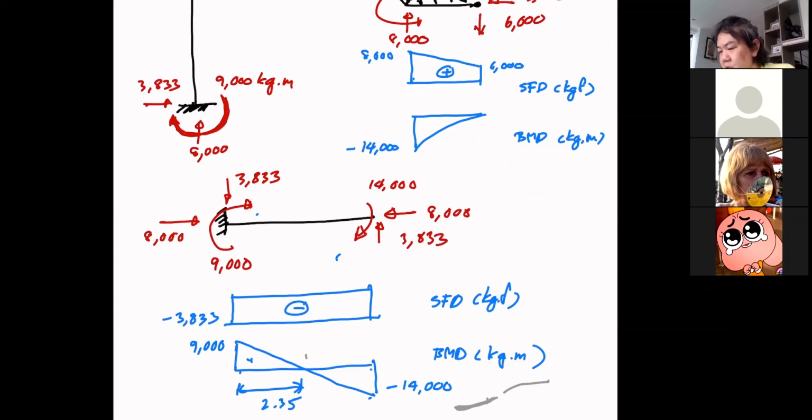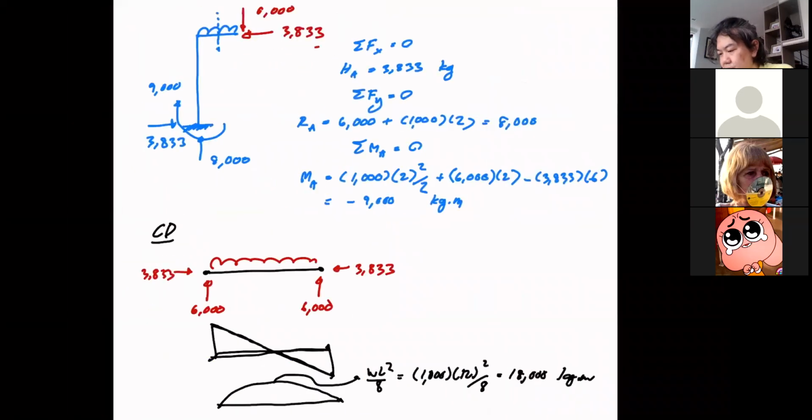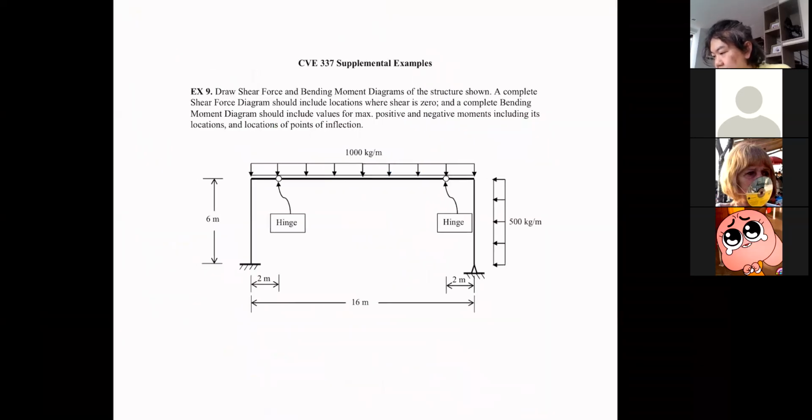So this piece will go just like this because of the presence of this, and because you have a 0 rotation there, so this frame is generally going like that. See? That's according to our bending moment diagram, right? You have a point of inflection where the curvature changes. And from your bending moment diagram, you know the compression is on this side. So it just has to bend like this, going in that direction.